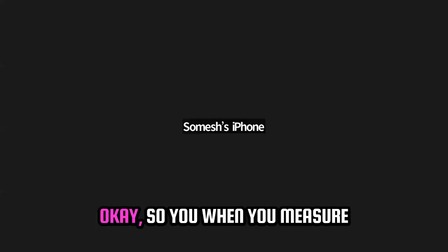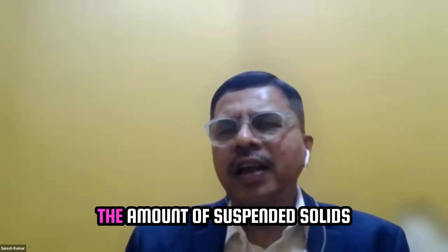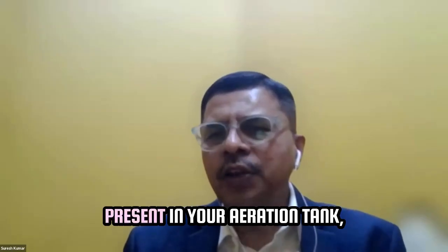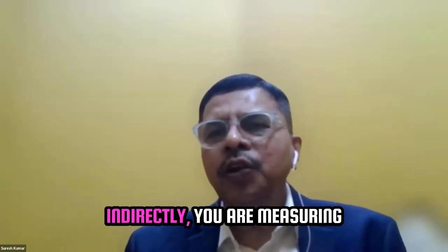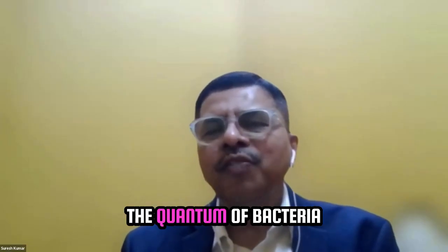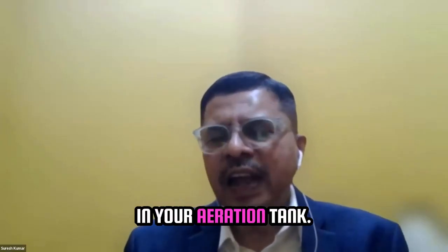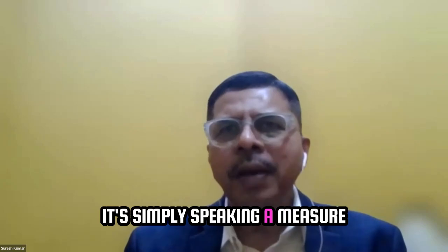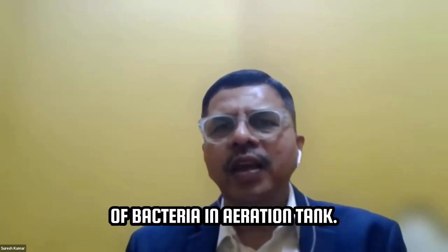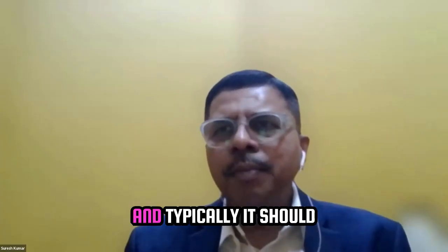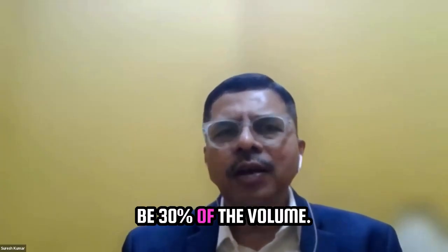So when you measure the amount of suspended solids present in your aeration tank, indirectly you are measuring the quantum of bacteria in your aeration tank. Simply speaking, it is a measure of bacteria in the aeration tank. And typically it should be 30% of the volume.